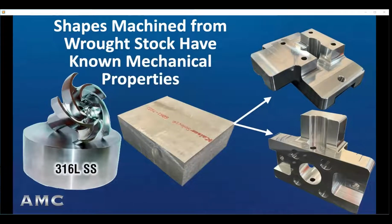Shapes machined entirely from a wrought block or part of a similar alloy already have the mechanical properties established in the block. Yes, there are differences in longitudinal and transverse properties depending on the orientation of the block or bar when it was rolled or forged, but as a machine shop, you know what those properties are before you start machining. So the machine shape can be oriented to best use the longitudinal properties of the part's structural strength.